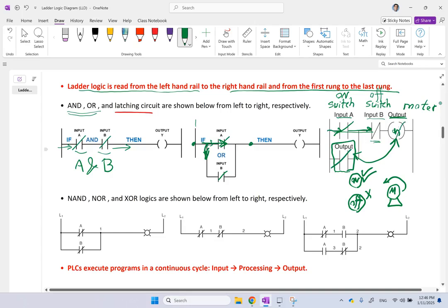Now, as I said, if you press the on button one more time, what do you want the motor to do? Well, it's the on button. Whether you press it one more time or two more times or 10 more times, if somebody by mistake presses the on button, you don't want the motor to turn off. You want pressing on to have no effect on running the motor whatsoever. It's only the off button that, if you press it, should turn the motor off. Pressing more on the on button should not do anything. Okay, so how do you do that?